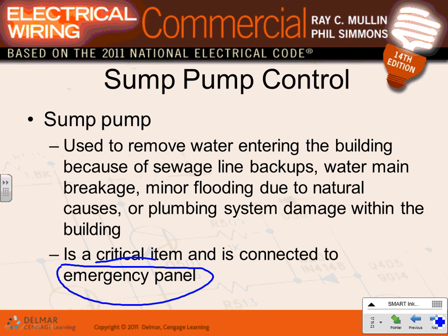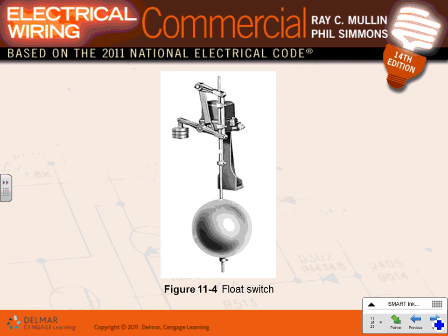You put that sump pump where? On your emergency panel. Do we have a generator, guys, in our building? Yes. So this pump is actually going to be on the generator because the generator is going to pick up the building. So it becomes a legally required standby. This is a legally required load. It's required if you have an emergency system to put that particular load on the generator.